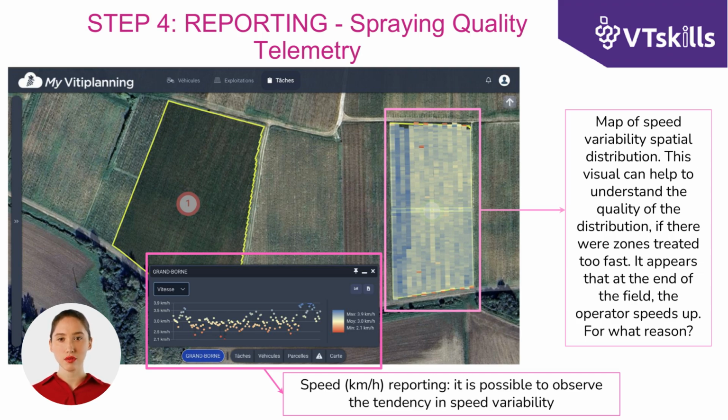DPA stands for directly proportional to advanced distribution, that is, the dose distributed per unit area is kept constant even with any variation in forward speed. Apart from rare cases of purely mechanical DPA controllers, most are controlled by an electronic control unit, which processes signals from flow meters, pressure transducers, and speed sensors. Nowadays, any sprayer machine at a certain level is equipped with them. DPAs are, in fact, not very recent, but still relatively expensive innovations.